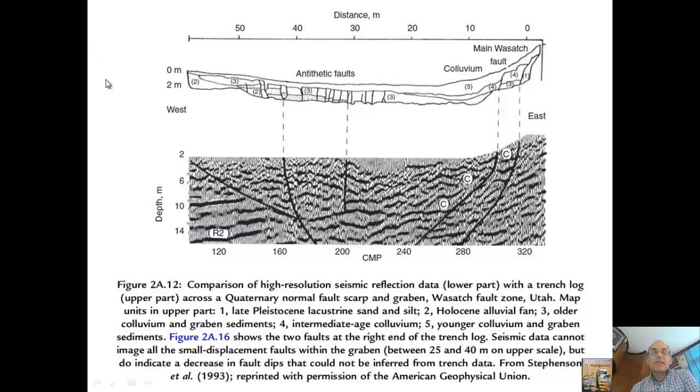So in that sense, the trenching confirms, especially right in this area, that there's really an offset, almost a meter, but there's been erosional modification above it. Then when you go into the seismics, you might interpret, as they have, that there's a bigger disruption in this area. That I don't see so much there. I guess maybe here's a break.